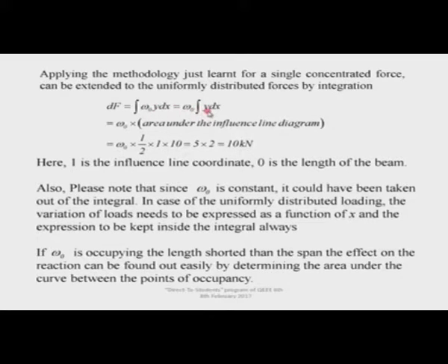Now, omega 0 has already come out of the integral because it is a uniformly distributed load, but if the load is not uniformly distributed, it will be a function of x, which I can express, or segment-wise I can express through different integrals. If I totally fail, I will have the summation over different ranges, no problem.